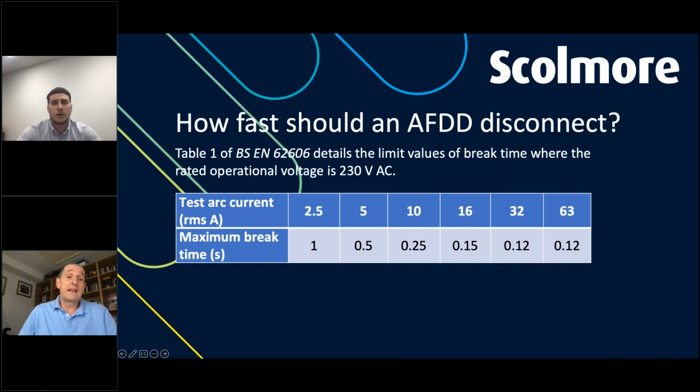Yeah, more modern properties will have LEDs, they'll be drawing much less. So you're just simply not going to have the current there to trigger this parameter. Now, if you're working somewhere like where I am now in an office, you may be sitting there thinking it's got merit, it's got benefit of being on there. It's going to be that test current. We're going to see an operational change when it comes to a 6 amp device.